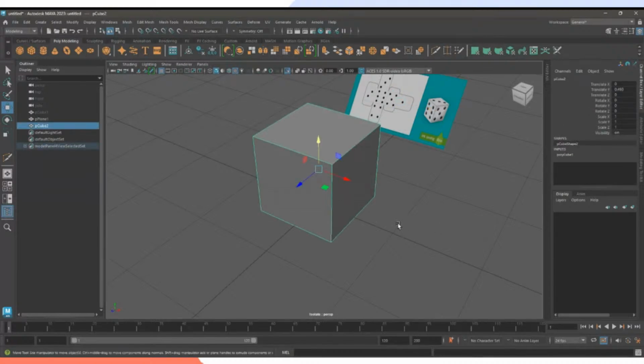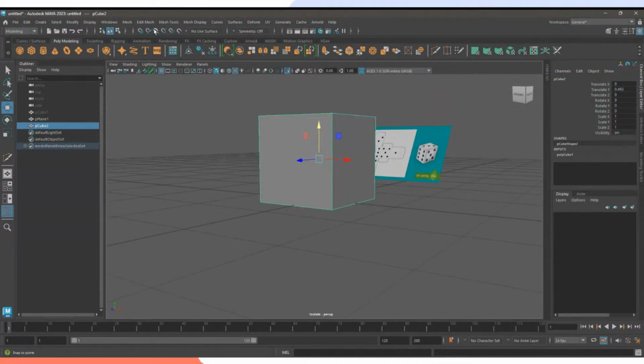One of the things you can do here is have it snap. Like snap to curves, snap to points, snap to projected center. We're gonna be snapping this by snap to points, pressing and holding the D key, and then just pressing down on the arrow axis, the arrow pivot, the yellow one that represents the y axis.